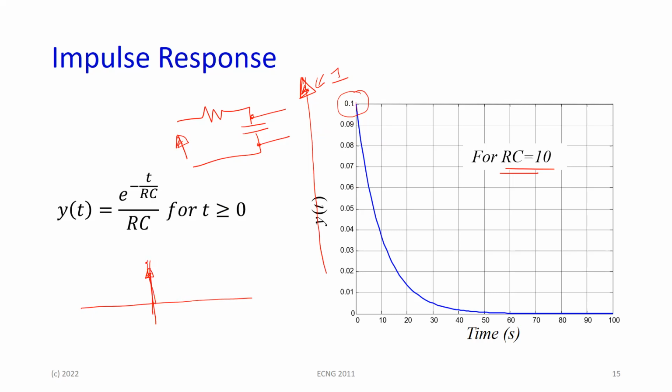Sometimes it will go immediately to VCC and stop, fuses blown, etc. Other times it will get to a fraction and then settle down again and switch itself back off. This is a good response. Nothing has blown. What could have happened is that it just went and then the power supply or the fuse blew. If you make R and C too small, that may very well happen.